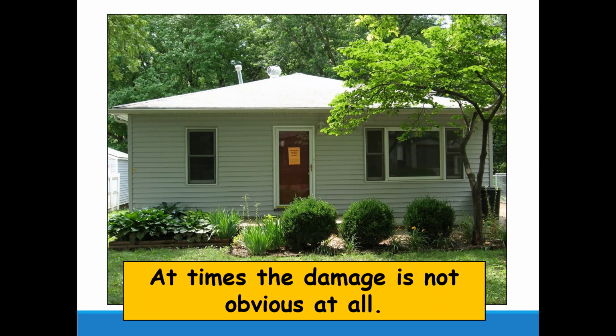Just again, yeah, being careful. So the entire back half of this house is just hanging out suspended over the air. And so it does have a substantial damage tag on it and it says uninhabitable and all of that. So you start with your windshield inspection and you make a list of what's low damage, what's definitely high damage, and what you think is medium damaged. And then you actually start with the medium damage.